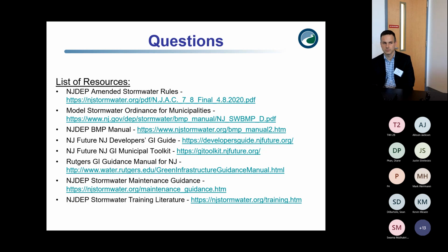Thank you. Andrew, do you have a question? A request, I guess, for you and anyone else who's trying to naturalize an existing basin or design a new bioretention system. When you're doing this, have the first 5, 8, 10 feet around all of your hard structures mowed and cleared so that your municipalities can come in and do their inspections without getting ticks and asking you to go clear this area so that they can actually see the structure, and berms as well, so that we can make sure that there's no tunneling. Absolutely.